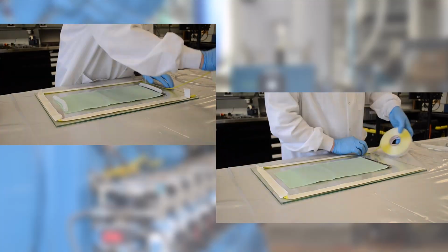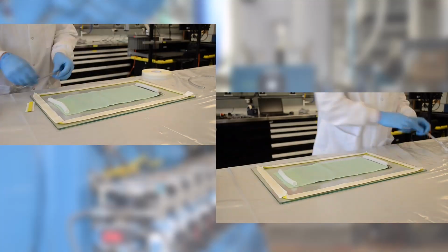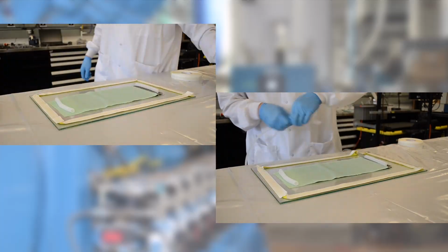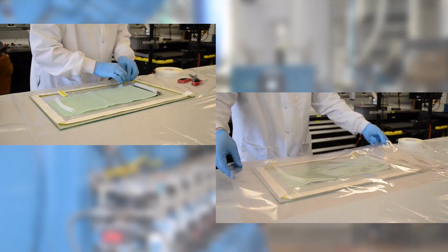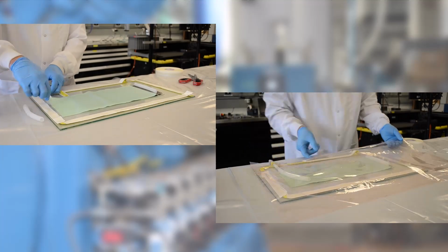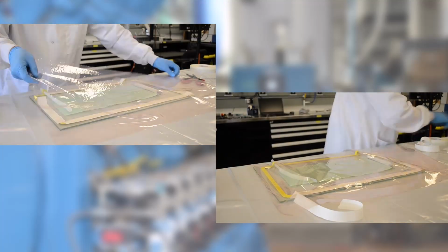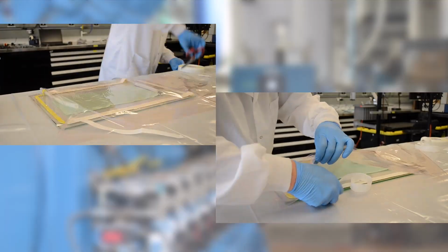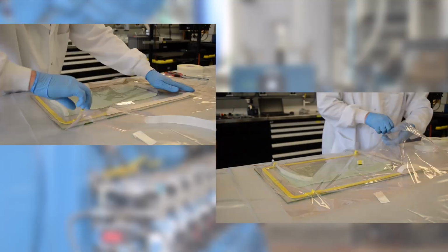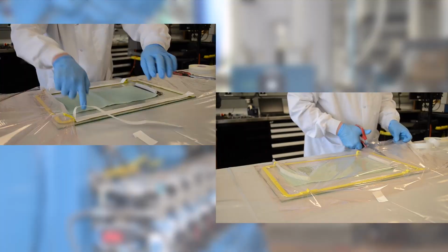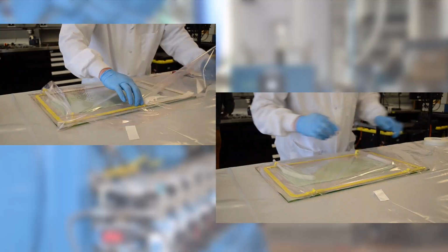Imagine you wanted to calculate the permeability of two identical parts. You would find that the individual permeability and flow front versus time values may not match up perfectly. There are many reasons for the difference in these values. However, the most common reason for this is experimental error. Each time the vacuum infusion process is executed, the environmental and human errors are greatly varied.